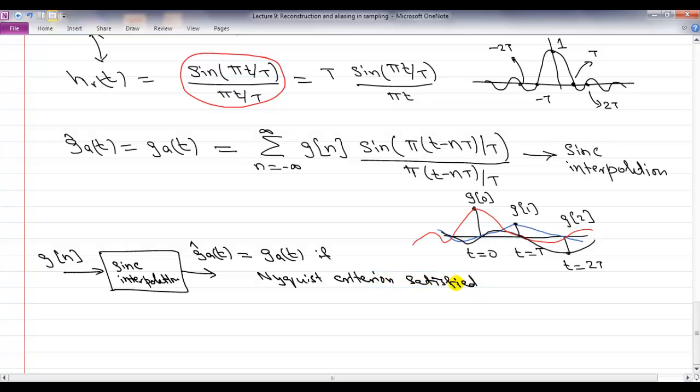Now, in reality, what happens is that to do sinc interpolation, you need to add up an infinite number of sincs which are effectively going from minus infinity to infinity. Okay. So these sincs have a range from minus infinity to infinity. You can't really implement them in practice. And what people do is approximations to these sinc interpolations, which is effectively approximations to low-pass filters.